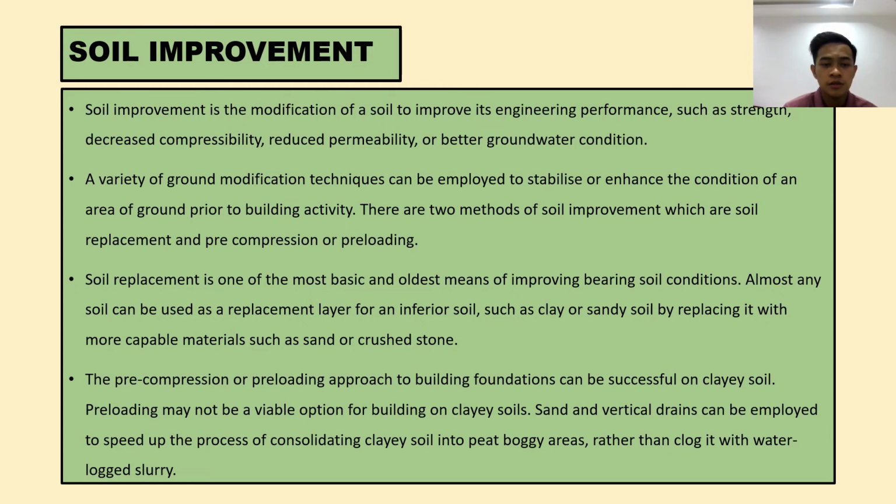Soil replacement is one of the most basic and oldest means of improving bearing soil conditions. Almost any soil can be used as a replacement layer for an inferior soil such as clay or sandy soil, by replacing it with more capable materials such as sand or crushed stones.